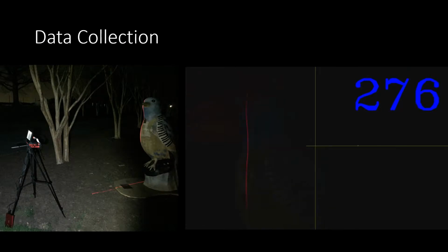The unique capability of my Lidar sensor is that it scans from left to right as opposed to up and down, measuring each angle with a compass. This was to reduce the moment arm of the vertically positioned mount by rotating it on its side, which also reduced the effect of wind, and to mount an external display to make the system stand alone so I was not reliant on Wi-Fi or other systems.